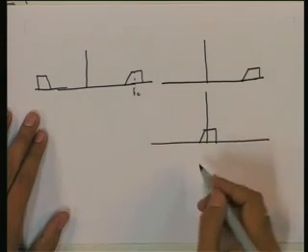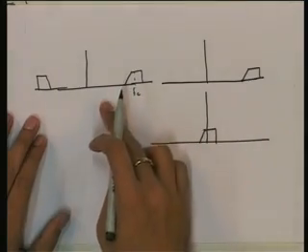We have seen the relationship between this signal and this signal, and in particular we have seen how to construct the bandpass signal from the low pass equivalent signal and how to construct the low pass equivalent signal from the bandpass signal. The bandpass signal is a real signal, but the low pass equivalent signal will be a complex signal, because there may not be any symmetry in one side of the bandpass signal. Whatever is there in the positive side will also be there in the negative side, with phase negative, but magnitude the same. But in one side itself there may not be any symmetry. So, when we take only that part and bring it to zero center, then we may not have any symmetry. So, the resulting low pass equivalent signal may be complex. In general it is complex.